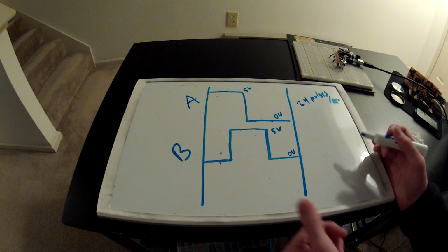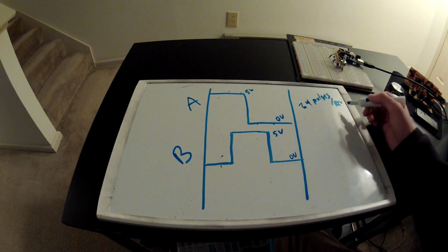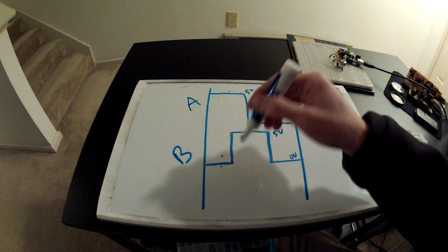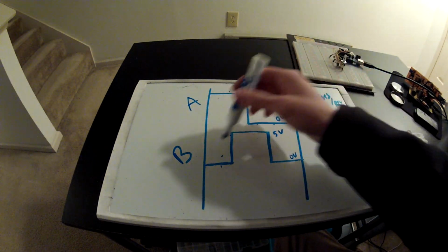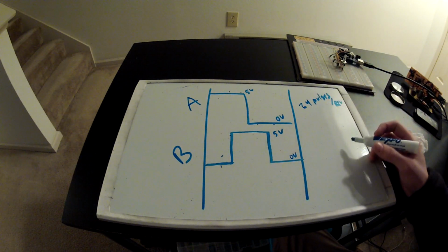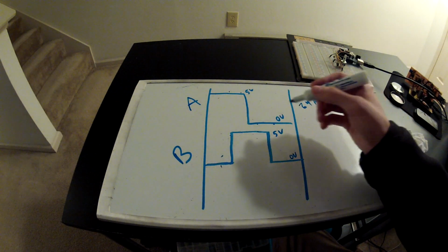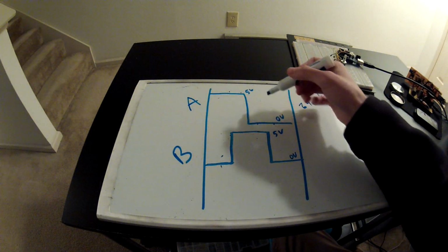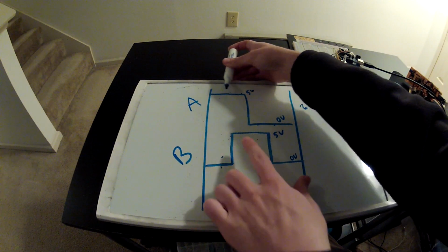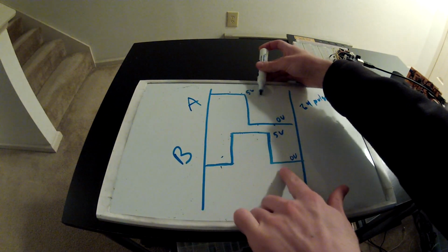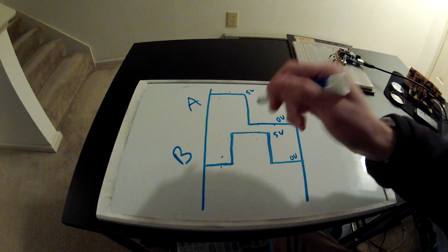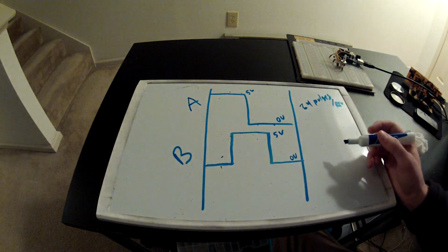All right. Now I want to talk about this 24 pulses per revolution. Since we have two signals and we have all of these different changes of states, we can actually increase that resolution a little bit, right? Because if you just count here, you basically have 1, 2, 3, 4 states that this thing can happen. So there's going to be 4 events in a single period.